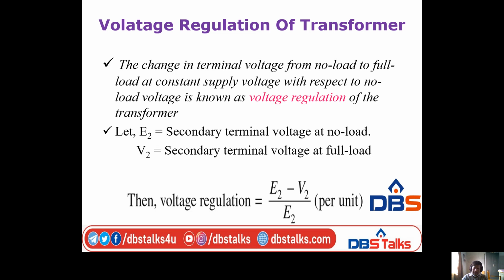So depending upon the load power factor, the voltage regulation also varies. If it is unity power factor, the voltage regulation gets a positive value. If it is a lagging power factor, it also gets a positive value. For a leading power factor, we can get a negative value, zero, and also a positive value.